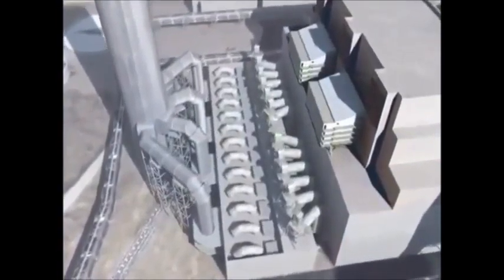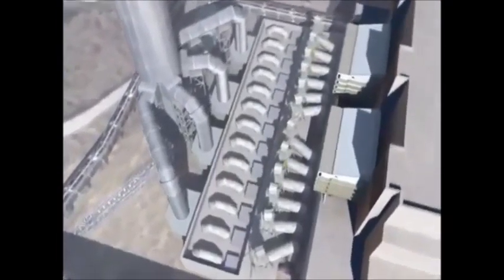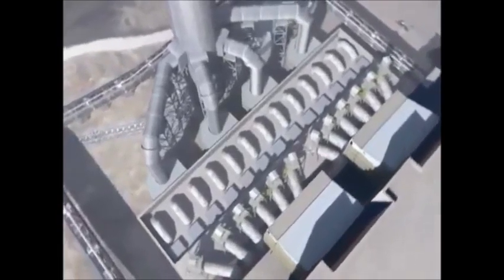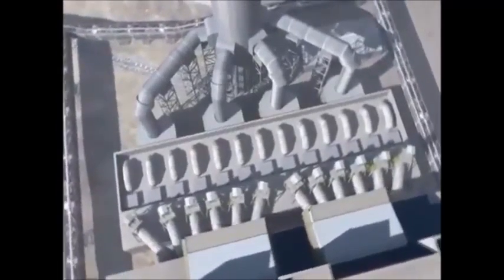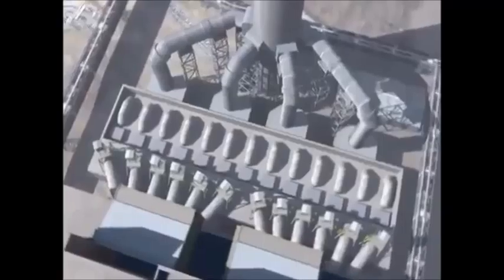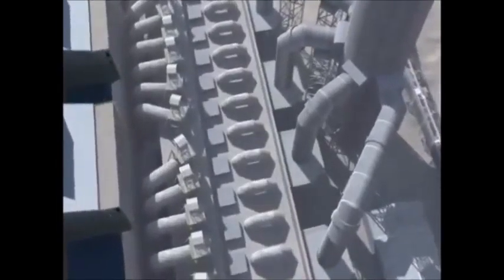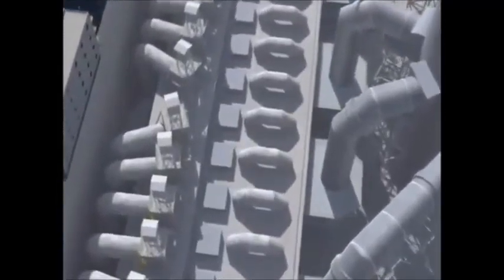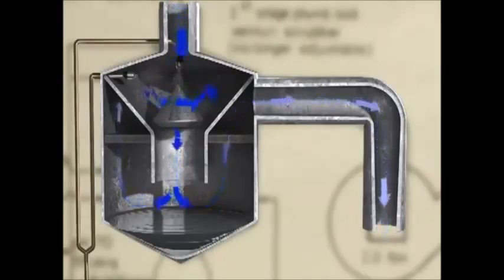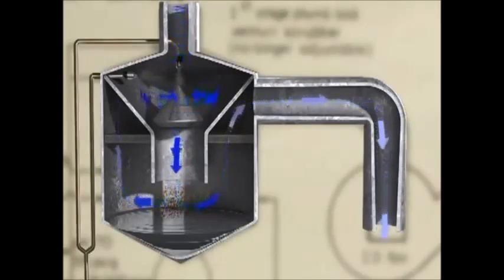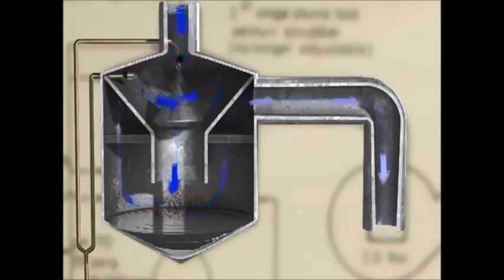Since 1971, FirstEnergy has spent more than $5 billion on environmental protection. Our plants are equipped with air quality control systems to remove sulfur dioxide and particulates called fly ash. Fly ash is removed by a mechanical process, and sulfur dioxide is removed with a chemical reaction using lime. These processes take place in large ductwork scrubber trains located between a unit's boiler and its chimney.